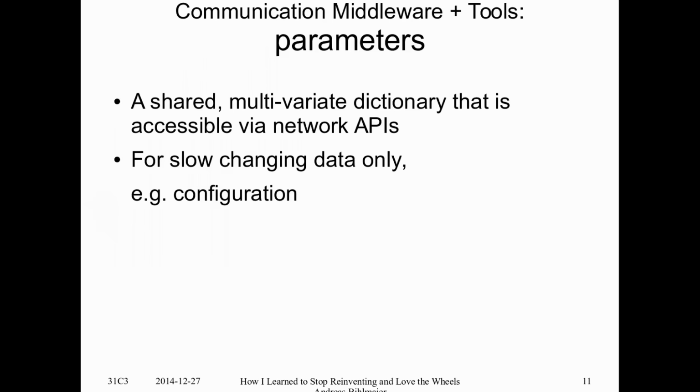And this is usually used to do distributed parameterization of your nodes. Imagine you have the classical solution of configuration files, and you want to run your node today on a different machine. Then you would have to make sure that your configuration file on this machine is up to date. With the parameter server, whoever in the network starts this node pushes the current set of parameters to the server, and all nodes, no matter on which machine they are running, use these parameters to set up their algorithms, for example.